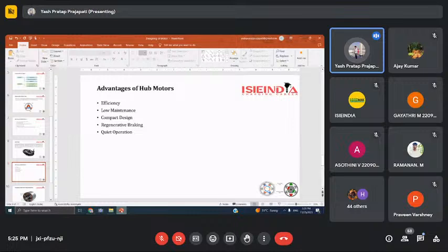Next, what are the problems of a hub motor? Like handling. Hub motors are bigger, bulkier, and heavier than ordinary wheels, and change the handling of an electric car or bike. They increase the unsprung mass, the mass not supported by the suspension, theoretically giving more shock and vibration, poorer handling, and a bumpier ride. That's the common wisdom. In practice, though, engineers have found that vehicles with hub motors simply need to have their suspension tweaked to compensate for the extra unsprung mass, and this can even lead to an overall improvement in handling.